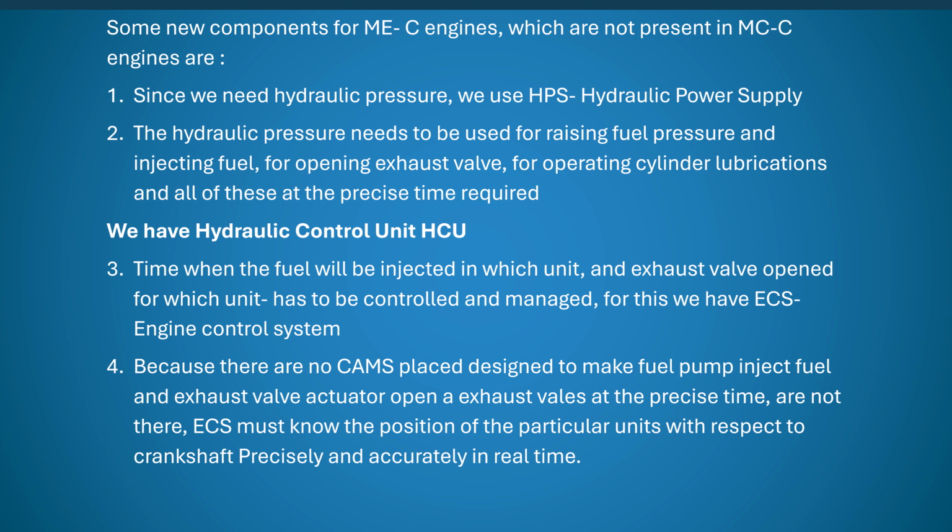The ECS must know the position of the particular unit with respect to the crankshaft, isn't it? Unless and until the engine control system knows the position of the unit piston with respect to the crankshaft, how does it inject fuel? It cannot inject fuel when the piston is midway.